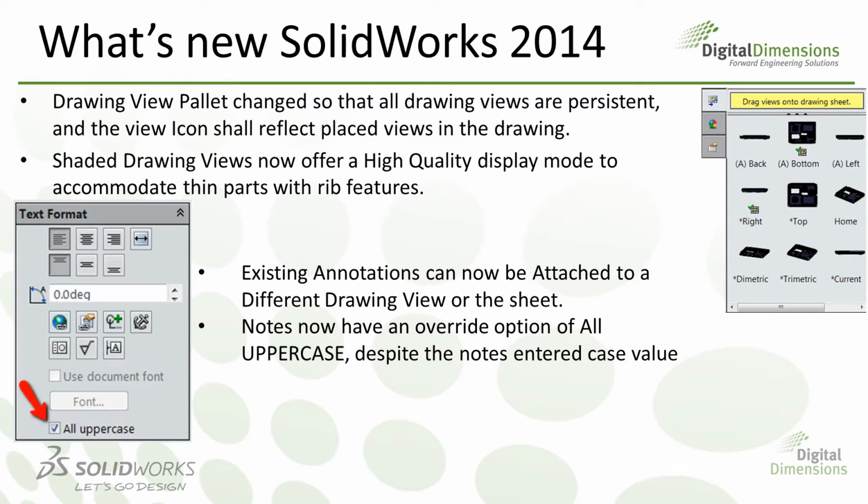The Drawing View palette has been updated such that all of your drawing views will now remain in the View palette even after being placed on the drawing. Any placed drawing views will now have an icon to indicate that they are inserted into the drawing. This will enable you to add the same view again within the same drawing sheet.